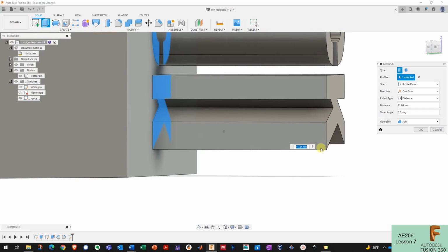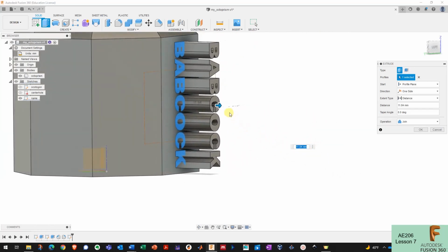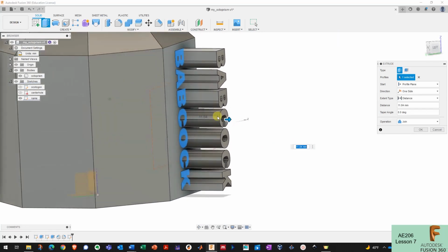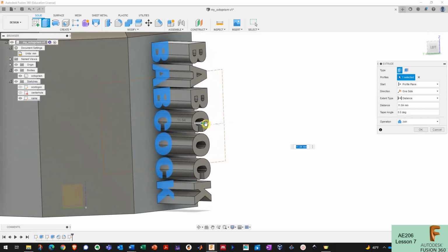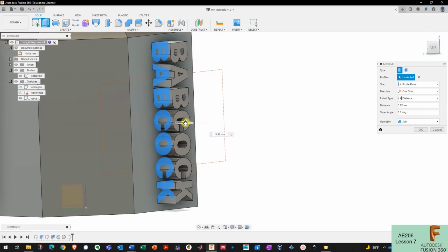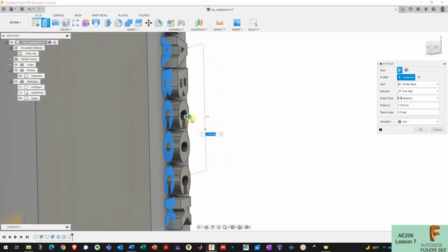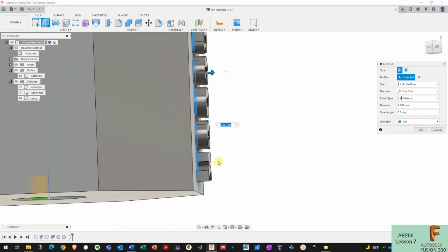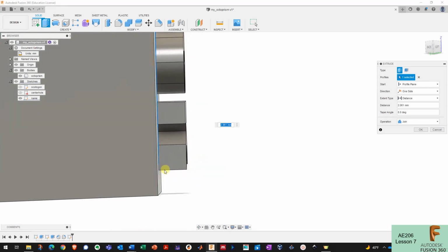And it's not going to be able to extrude it out on thin air, so it's going to require something called supports. And supports take up a lot of printer time, and they use up a lot of filament. And they also require you to remove them after the print is done, and they can affect the quality of the print. So when we're creating this octoprism, we want to be cognizant of the fact that supports are going to be required, and try to minimize those supports to minimize our print time and to make it look as good as possible. And what I've found is that if we emboss or deboss text that's 2mm or less, it can print this without any supports required, because the piece of plastic will just be attached to the main octoprism. It'll stick out far enough.